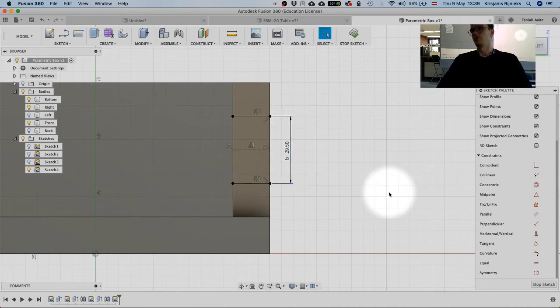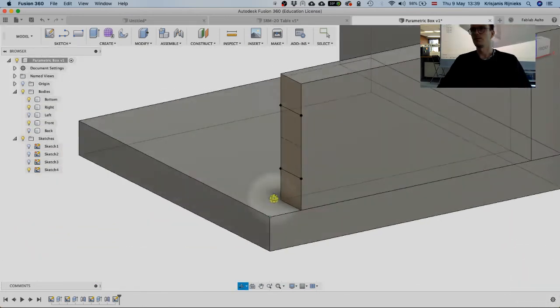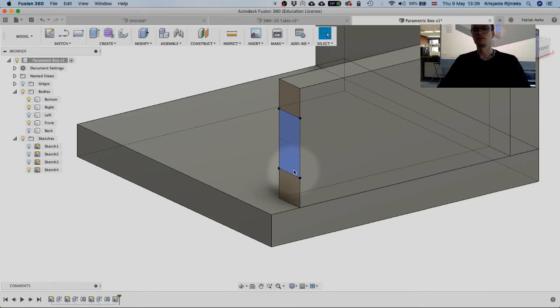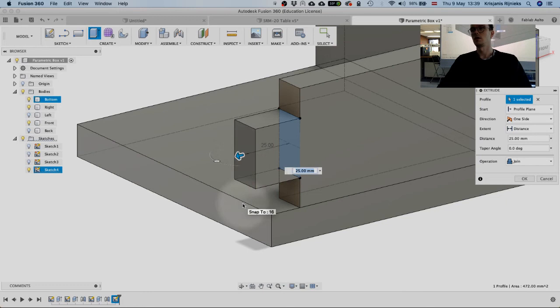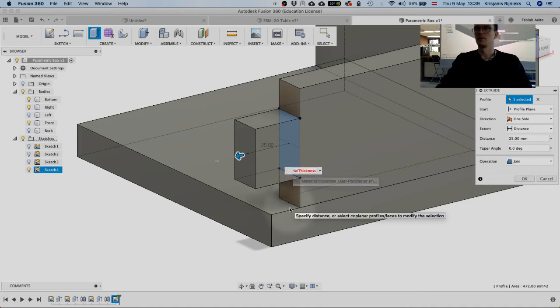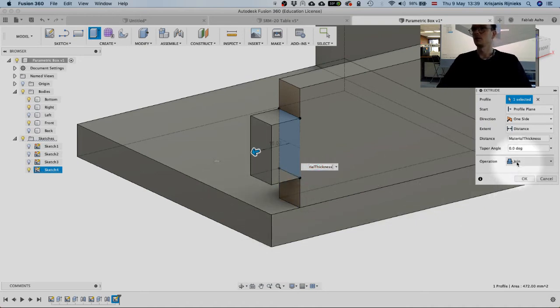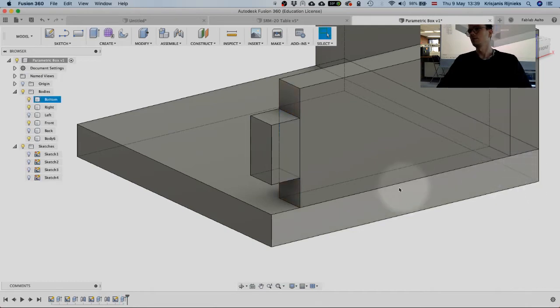This is going to be my finger joints, first one, and let's take a look at this sketch icon here. Yeah, it has the pins, it's fully constrained, it's all nice, good to go. And now we need to extrude it. I just hit E to extrude. And we need to extrude it by the amount of material thickness, since this space here is equal to that. And what we need also to make sure of is that we don't join it yet. So let's create it as a new body. Okay.